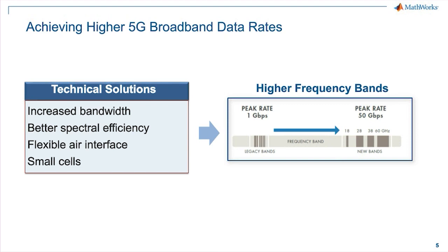And then if you increase the bandwidth, you need a place where a contiguous band of spectrum is available for this bandwidth. And fortunately or unfortunately, we have to go from our legacy mobile communication bands around 2 or 3 gigahertz to way beyond 6 gigahertz, which defines the millimeter wave. The minute you go to millimeter wave, the drop or attenuation in energy is so severe that you need to use MIMO techniques and multi-antenna to boost the signal, and that is essentially the way that we achieve better spectral efficiency.